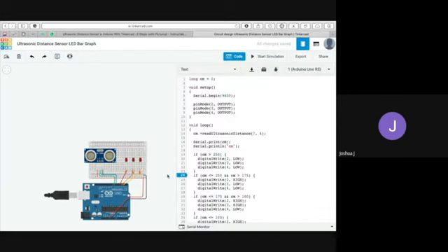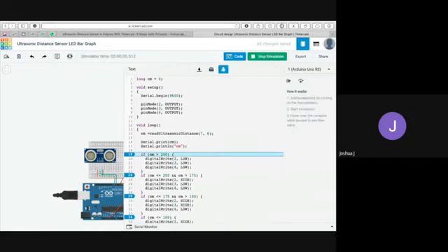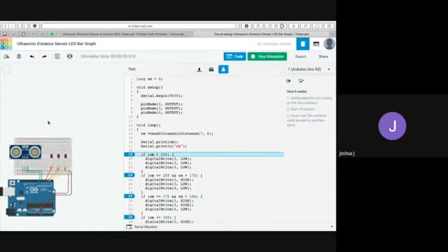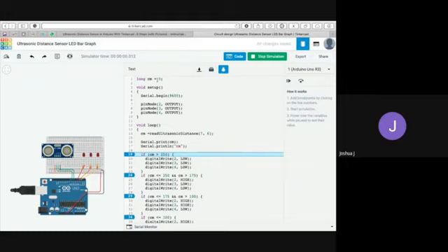Here, if you want to add breakpoints, have you used breakpoints in your program? Just click on these numbers and start the simulation. Your program will come and stop over here. Your program execution is an infinite loop. It will run, but it will stop over here.